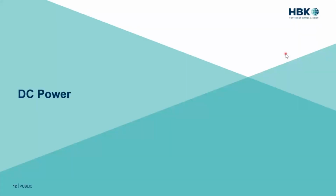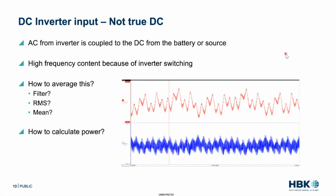So let's first look at the DC power example. Now I mentioned that these DCs connected to that inverter, that is not DC. If you short a battery, you see DC, but the inverter draws a lot, and you get current ripple, you get voltage ripple. So the AC from the inverter is coupled to the DC from the battery or the source, just by the nature of us turning this on and off very quickly. This high frequency content makes its way to the inverter.